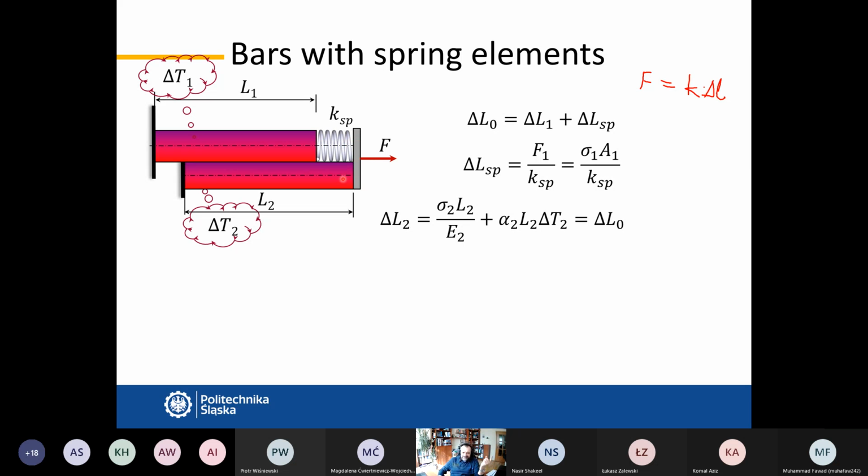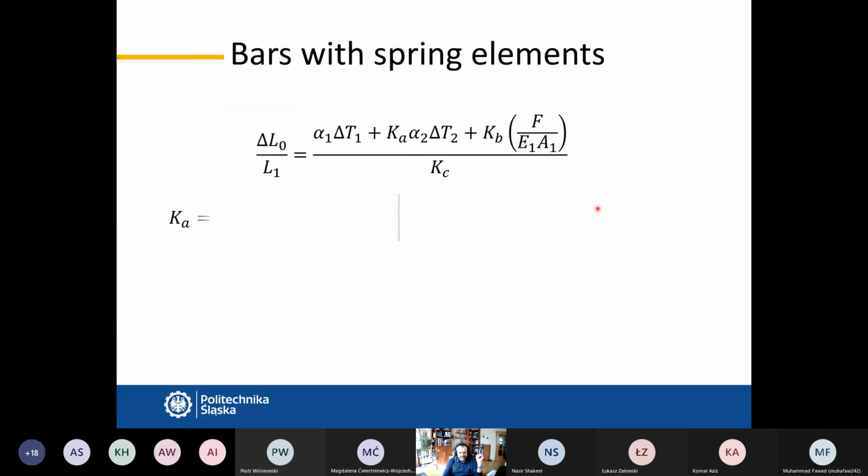So both bars can deform almost independently and they are unconstrained. So in such a situation, there is no stress inside. And the only stress that can occur in the lower bar results only from this force. So the magnitude of the force will be responsible for stresses. If there is no external force, the stress in the second member will also be 0.